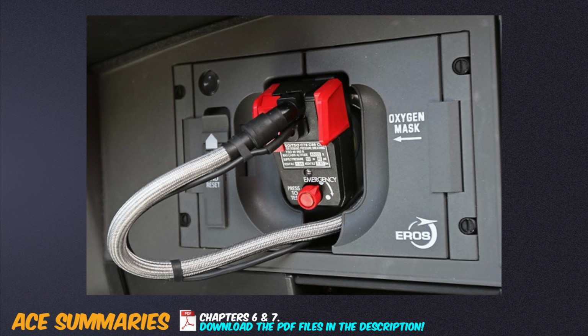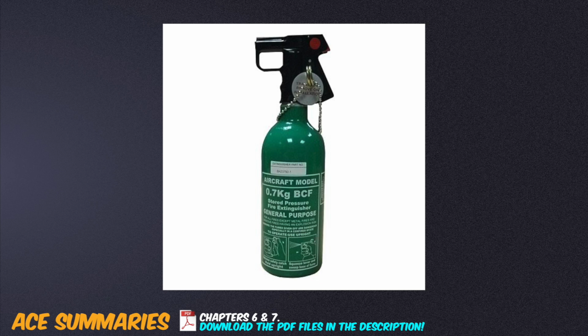100% oxygen can be delivered under two circumstances: demand and emergency. Demand shall be used for life support reasons to simulate a normal sea level quantity of O2. Emergency, for life support reasons above 34,000 feet, hypoxia, or cabin smoke. Emergency oxygen is not mixed with cabin air, is supplied pure and under pressure. Cockpit electrical fires should be contained using BCF fire extinguishers.